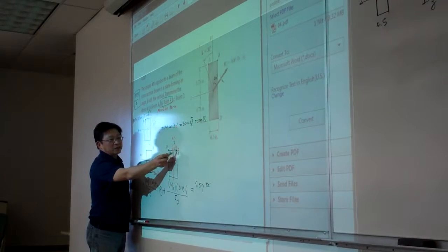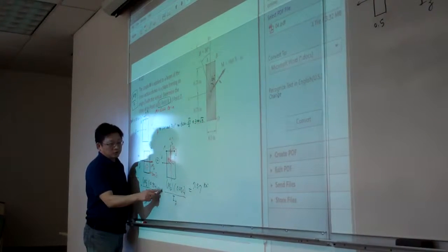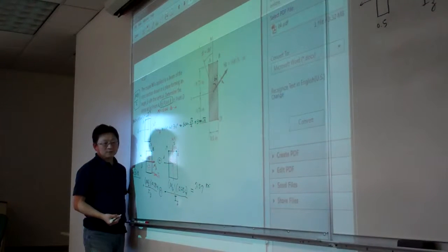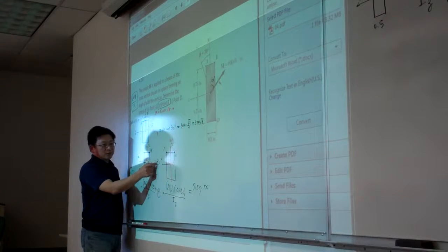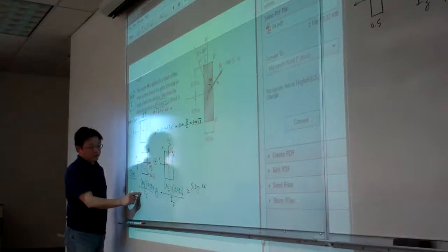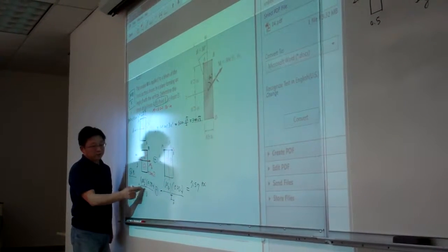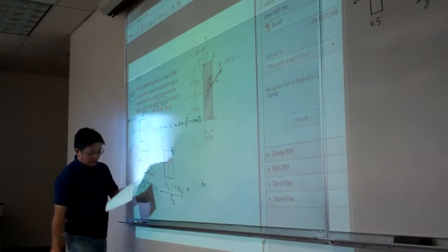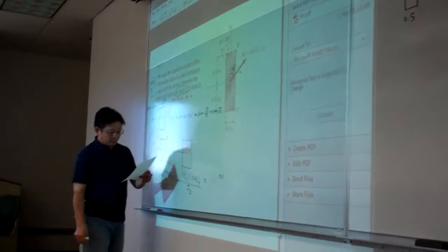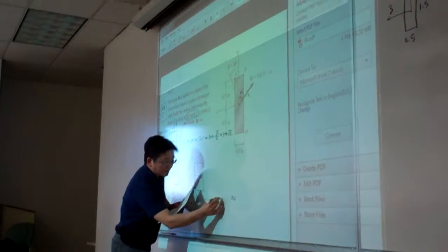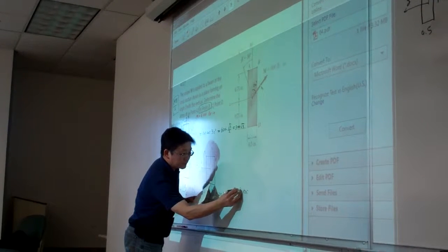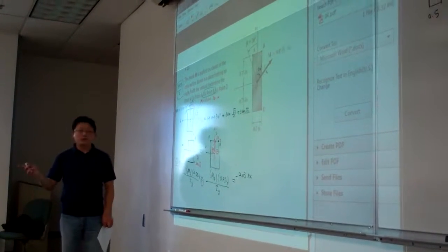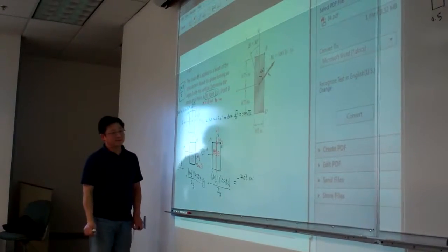Right now for this case, the B is in compression, so this one we add up is minus here, representing compression. And this is a superposition of the two cases. So plus is basically a positive term, minus a term here. So this number will become, would that be minus 2.03? Sarah, will that be this one? Yeah, I remember her name. I'm going to check. Okay.